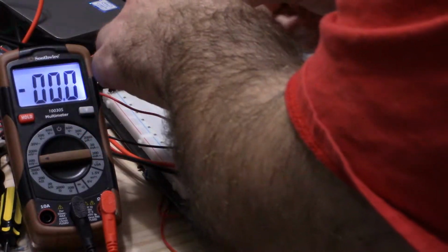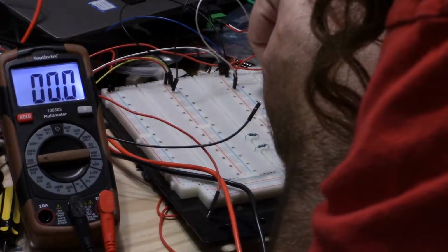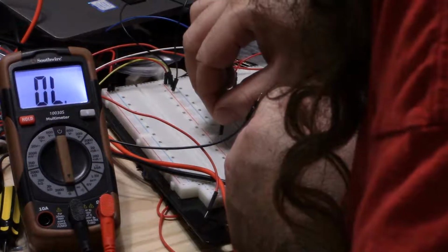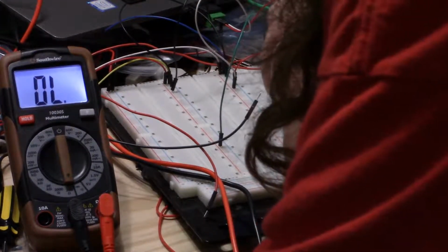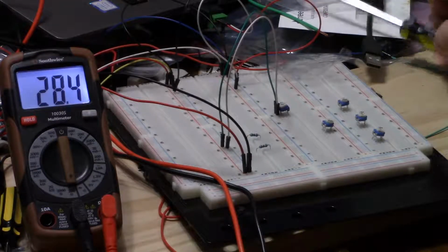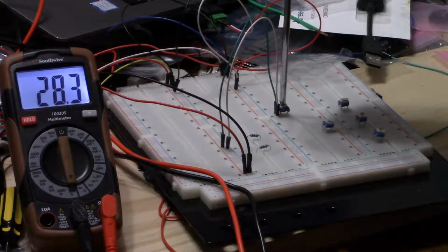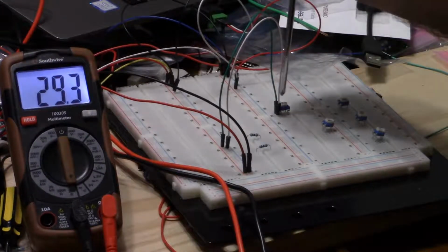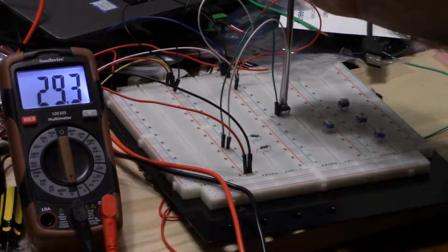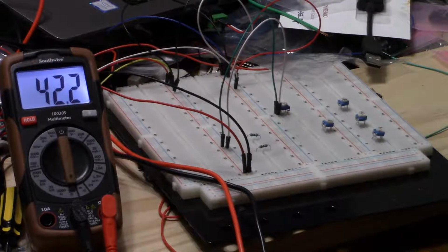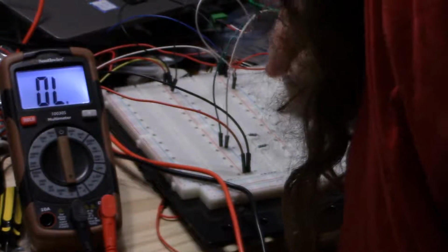So the first thing I'm going to do is measure the potentiometer. Let's put this in ohms mode. So I'll connect the potentiometer across the multimeter, plug the multimeter back in. I don't know why I unplugged it. And so I'm measuring about 28 ohms. Let me turn it all the way up. And I'm only getting about 27, 29 ohms on what's supposed to be a 100 ohm potentiometer. Oh, aha. I apparently have it wired backwards. Hold that thought. Yes, I have it wired backwards.